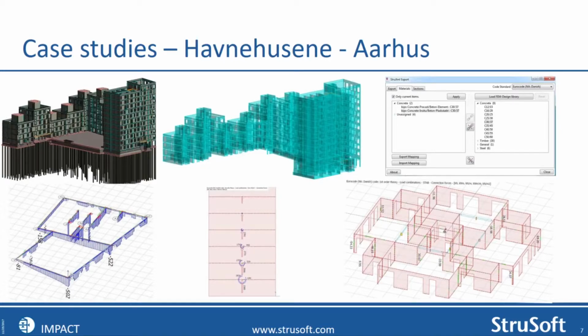And you can see the blue, which looks like a ghost city or something like that. But all the blue is the structural elements, which means the elements that help carry the loadings. Then we have a mapping function. We need to translate from Revit language into FEM design language. And in Revit, you can call a material whatever you like. So we had an example here called BIPS concrete in situ beton plastøbt. So we need to tell that this material in Revit corresponds to this material in FEM design. So it's like a dictionary. And this we need to do to make sure we don't get a Google Translate function. So we need to control manually how this is translated.